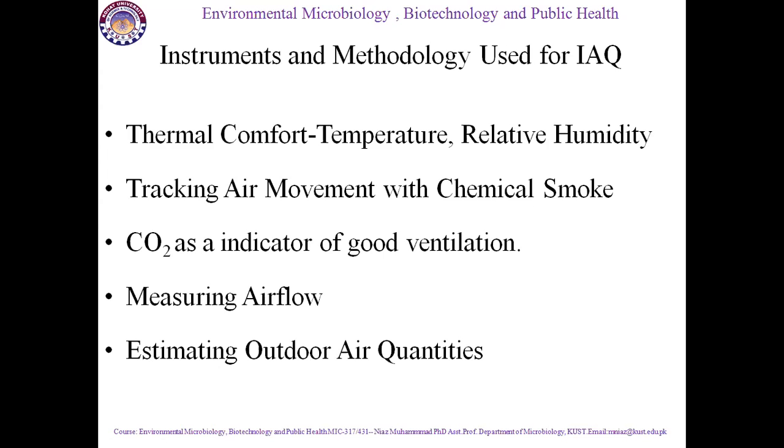Estimating outdoor air quantities and qualities, we must check the surrounding air. If there is a nearby plant emitting nitrous gases, carbon dioxide, or other gases, the concentration of those gases travels toward the building, and inside the building their concentration becomes very high. So we must take care of this.